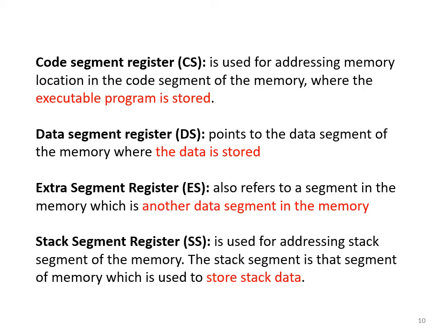And sometimes you need extra data segments, mainly for string applications, and that data will get saved in the extra segment part. Then similarly you have the stack, where the stack will come into the picture for programming. Suppose you invoke a subroutine call, then when you invoke that subroutine call, you need to come back to the previous location from where you called that subroutine, right?